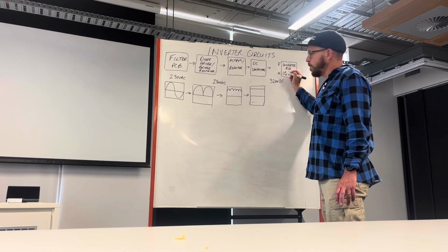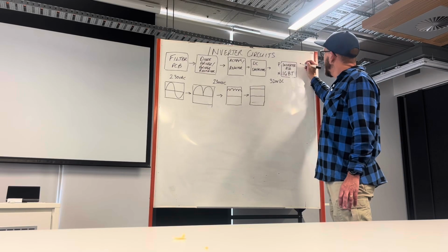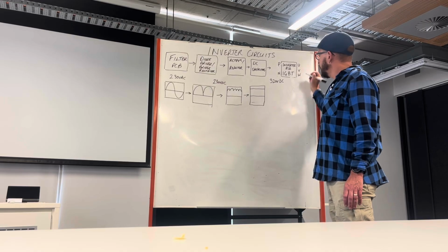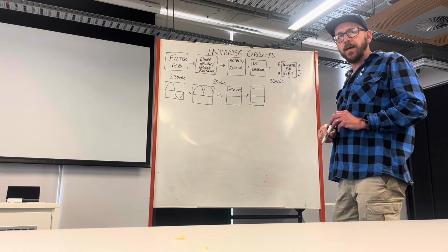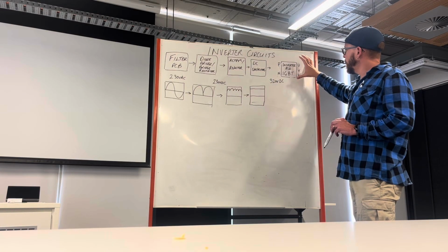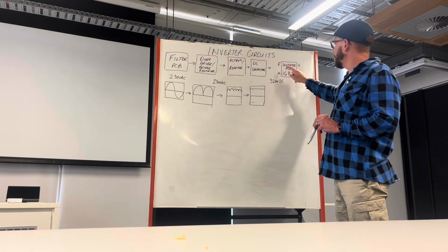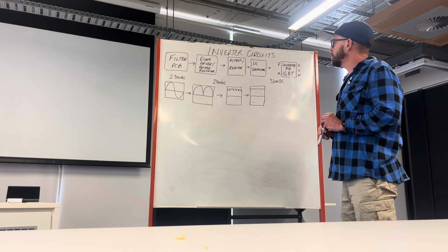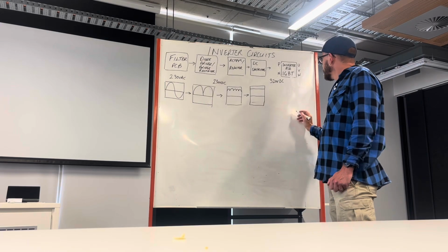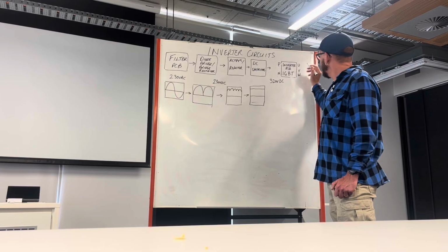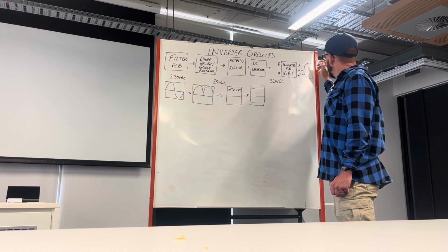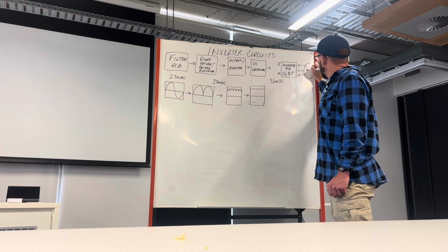Typically when we're looking for this component on our boards, we're looking at P and N, and on the output side of the inverter, we have U, V, and W. The three phases going down to my compressor. Regardless of the brand, typically if we're looking for the inverter chip on our board, we're looking for P and N, U, V, W, and those three phases are going to be coming down here to drive my compressor. So I'll have them coming off. I might just be able to fit this in here. That's my compressor.